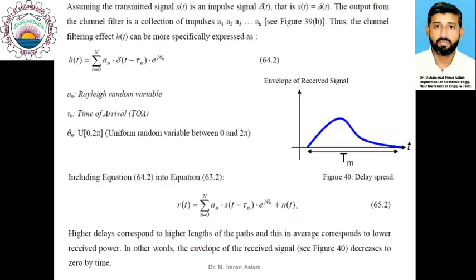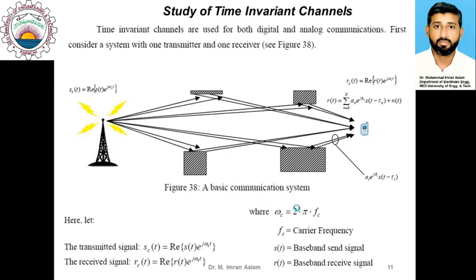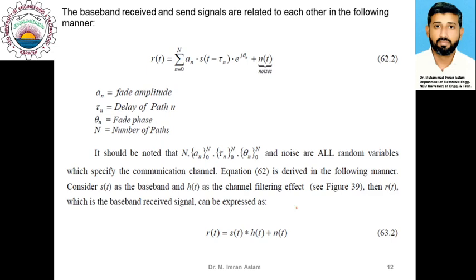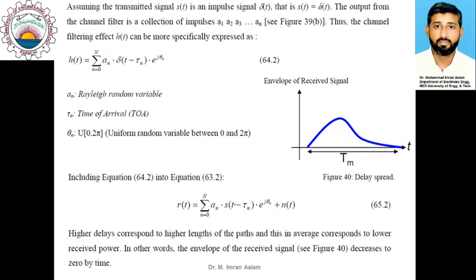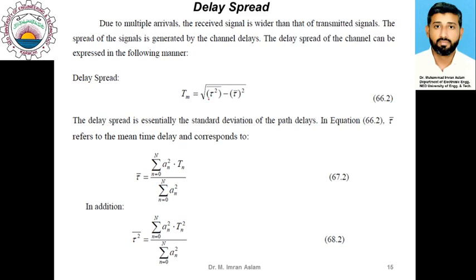So far we have discussed multipath propagation, and we have discussed that because of the multiple arrival of rays, we generally have arrivals at different times, and we get some delay in the received signal, which is measured in terms of its delay spread, or RMS value of the delay.